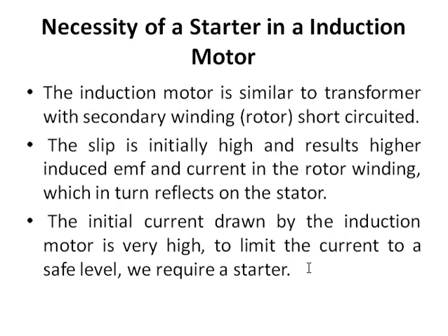To limit that current to a safe level, we require a starter. Because of the way the induction motor works, its secondary is shorted, so it results in a very high induced EMF, that in turn results in a very high rotor current, that in turn gets reflected onto the stator, and that high amount of current is not desirable. So we want to have that current at a very safe level.